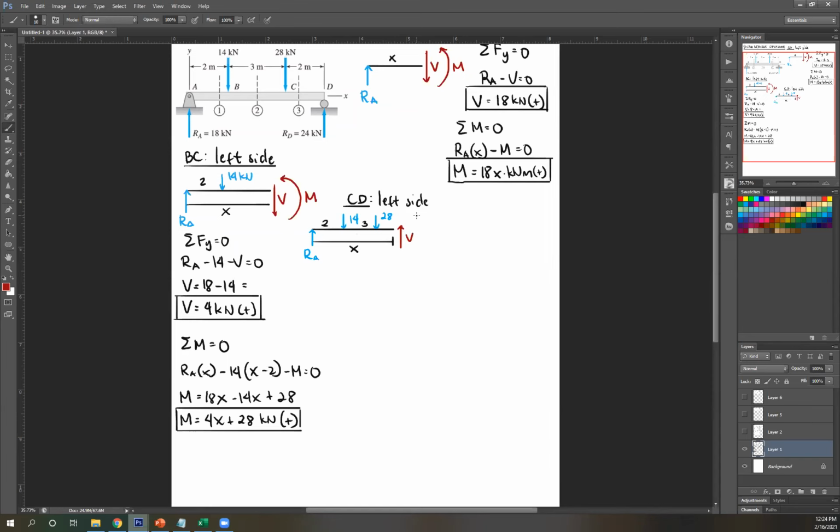Next, since the greater external force here is downward, figure out how it's gonna rotate about your segment. It's gonna rotate, as you can see, counterclockwise. So therefore, to counter that, my moment should be clockwise here. So clockwise is this way. That's it.